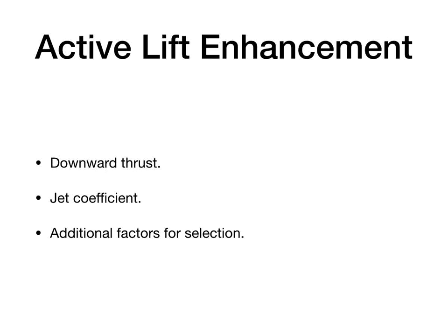The externally blown flaps approach only directs the hot exhaust over the flaps, so the area of heat resistant material that has to be covered is less than with USB. This makes the weight penalty less. This and its relative simplicity may be the reason that the EBF approach appears to be the most popular means of active lift enhancement used by aircraft manufacturers.